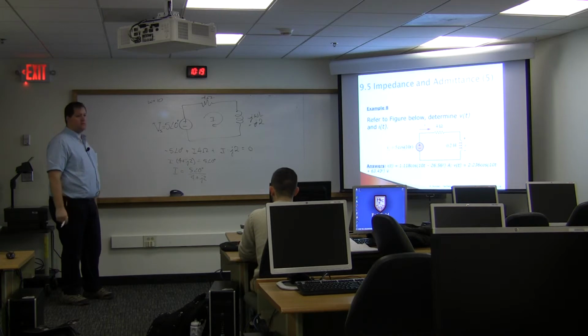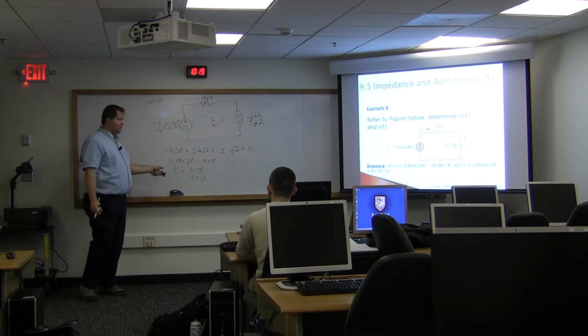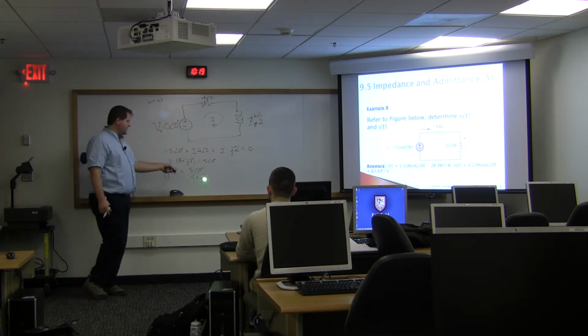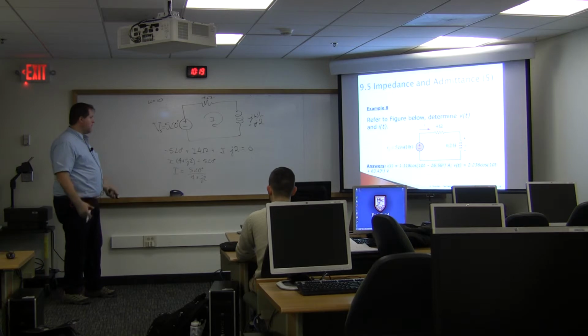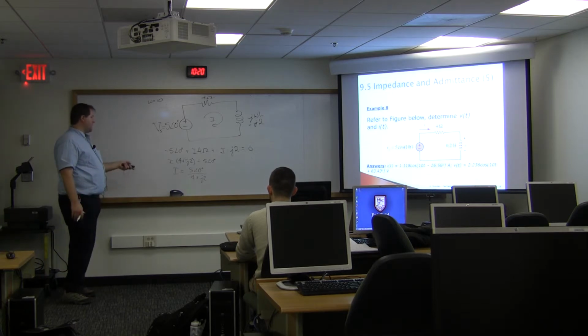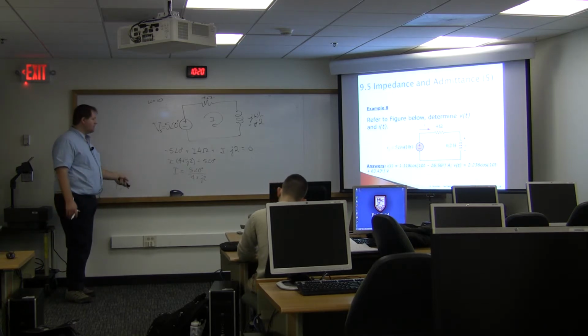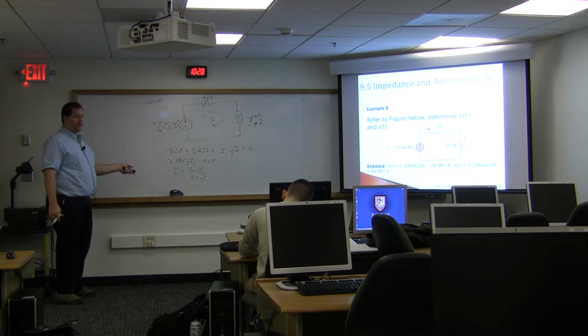That's my answer. Now I need to do a little bit of the complex number gymnastics here to simplify this. Right? If I'm doing it by hand, I should put the denominator into polar form. So I'd have to take the square root of 4 squared plus 2 squared. So that's 16 plus 4, square root of 20, which is not a nice number, right? So it's 5 divided by the square root of 20, and then you subtract the angles, right?